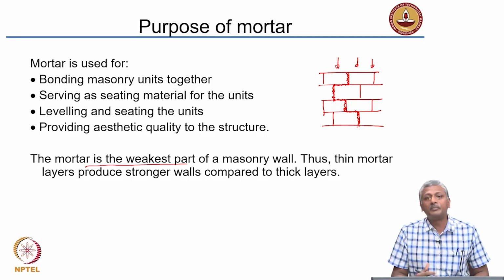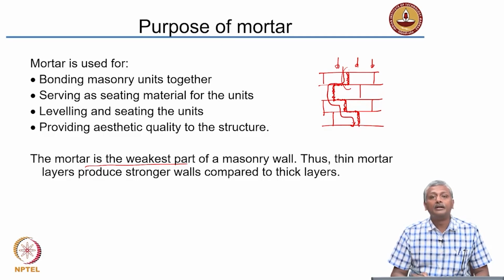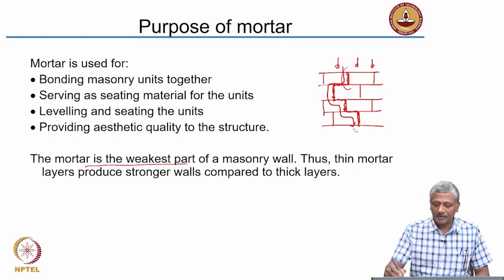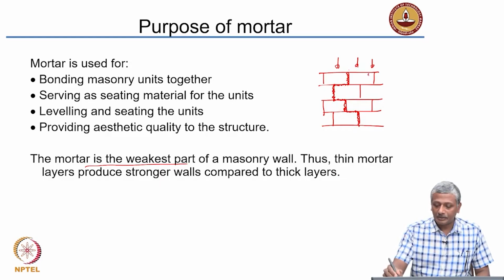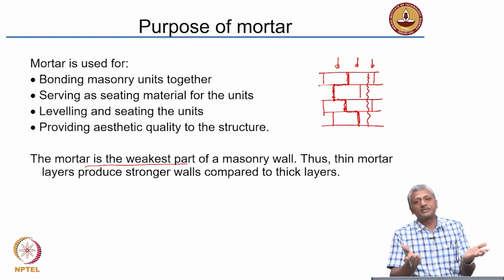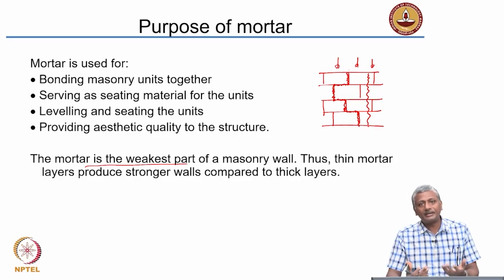Okay. So, the building will fail because of failure of the mortar joints, and that will be a slow and steady failure because the crack has to travel a longer path. So, it needs to come like this and come like this and like this and go. On the other hand, if the mortar was strong and the masonry material was weak, the failure would be completely different. You may have a cracking right through like this. So, entire building may just split into half because the masonry material, that is a brick or the stone, is weaker than the mortar. You have used a mortar which is very strong and it does not fail at all.